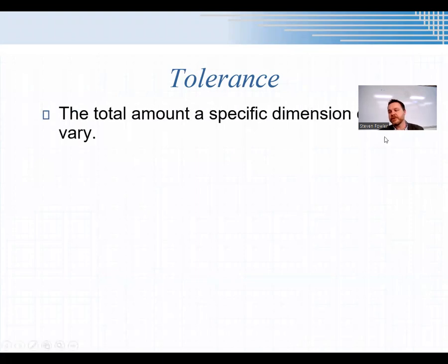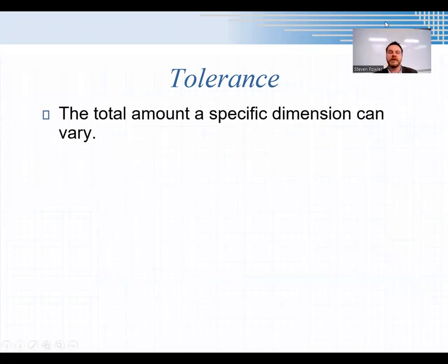And so to talk about tolerances, we've got to lay down some base theory first, but let's talk about what tolerance is in the mechanical sense. When we're talking about tolerance, we're talking about mating parts, objects that are designed to fit together. Okay? And so when I'm designing things to fit together, the simplest thing to say is they can't really be the same size. I mean, they could, but that presents a number of challenges, and we'll see that, especially as we start 3D printing things for the final project. The idea of tolerance is the amount that something can vary and the parts are still functional.